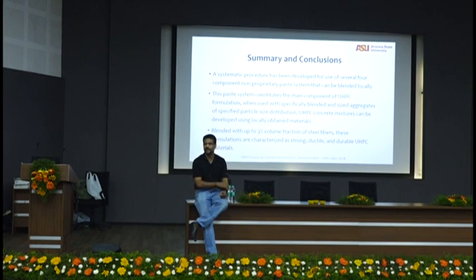We got about 175 in the lab. In the field, they got 200 megapascal because their field mixers are much better than the lab mixers. In the lab, I have my big lab rotary mixer, but in their field mixer, with all the mass that goes in, they had a much better mixing, and fibers distributed really nice. About 192 megapascals or so at 90 days, which is way more than what was specified. They wanted 150, we got 150 at a fraction of the cost that they would have spent.